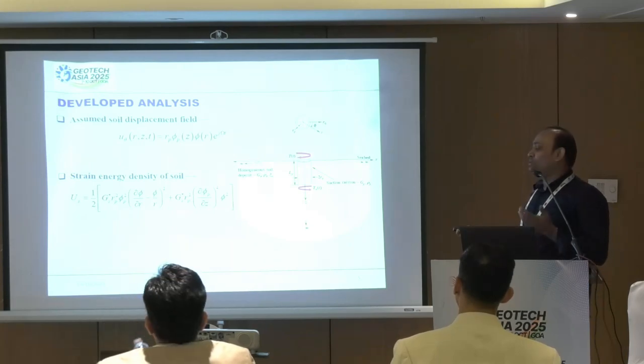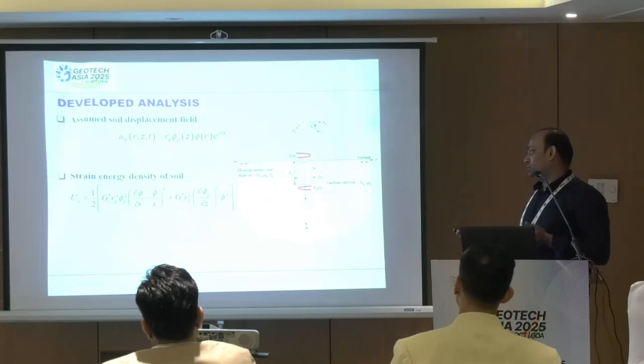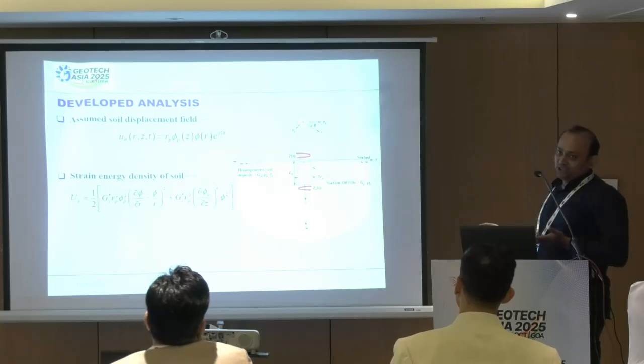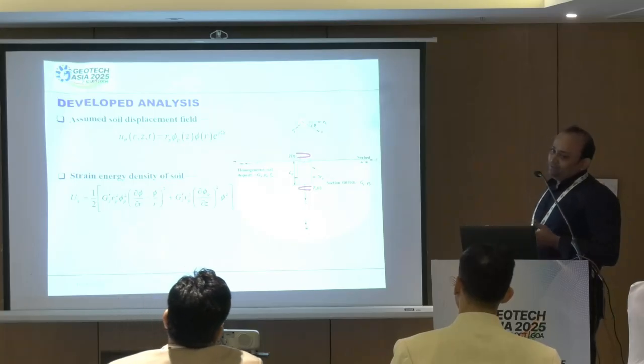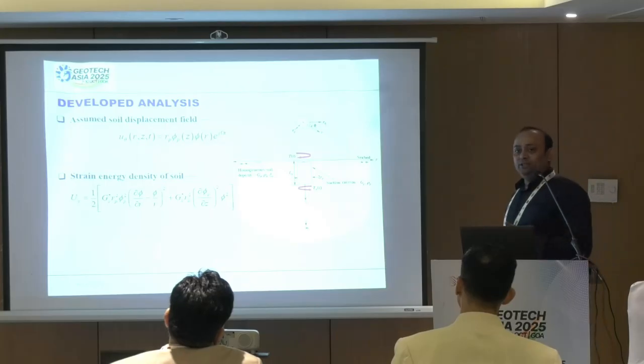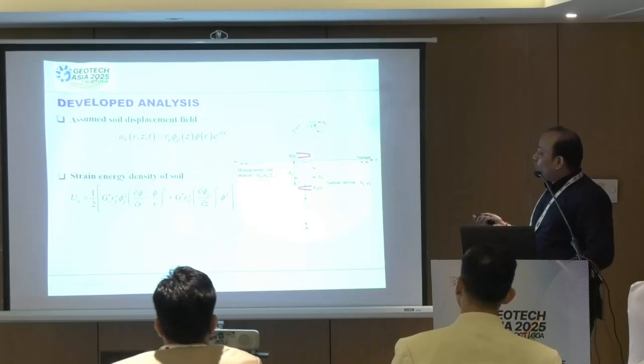Because this is a torsion load, so you usually take into account the shear modulus of soil. Dynamic, so density is coming into picture as well, because inertia effects will be there. And then you have this material damping ratio of soil. And the properties of suction caisson are also given, which is basically the shear modulus of the caisson, denoted as GP. And then obviously the inertia effects of the caisson will also be there in case of dynamic load. So you have rho P.